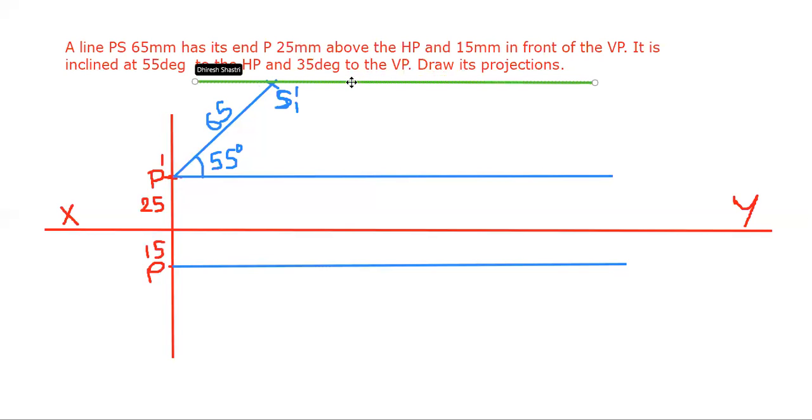Say this is a locus line. Okay. After that, through that point, you have to draw one vertical line up to the horizontal line through P, the horizontal line going through P. You have to draw one vertical line up to it. Your next step again is to take an angle with VP.